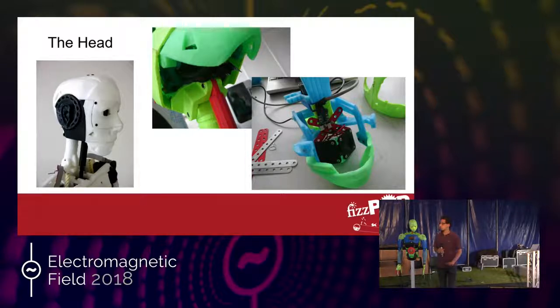The amount of data coming from both cameras would cause connection problems. The only solution is to reduce the resolution coming from the 2 cameras, which then cannot really provide enough data to do any processing on stereo images. So if I am to rebuild this, I will stick with a 2-camera solution.